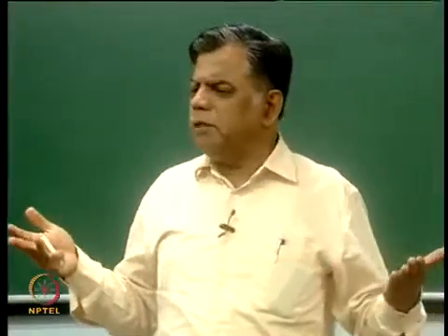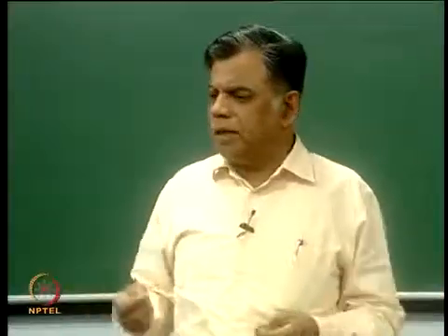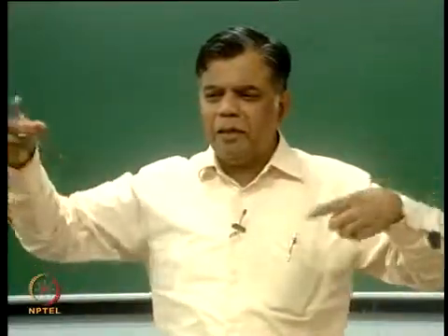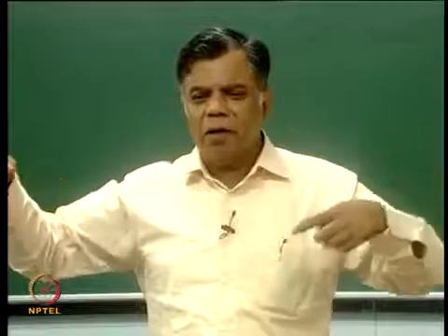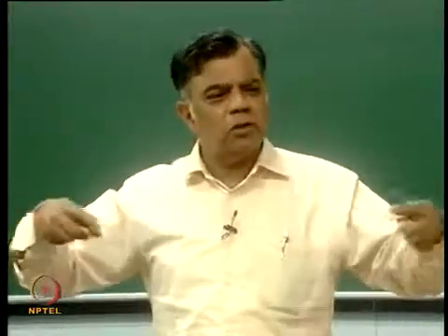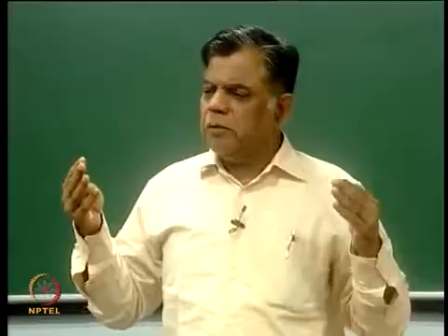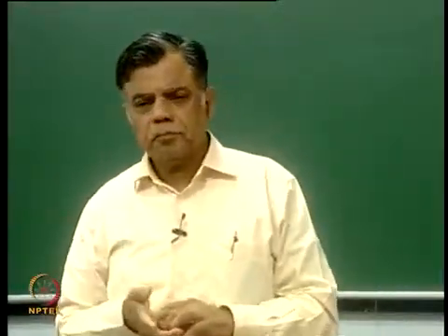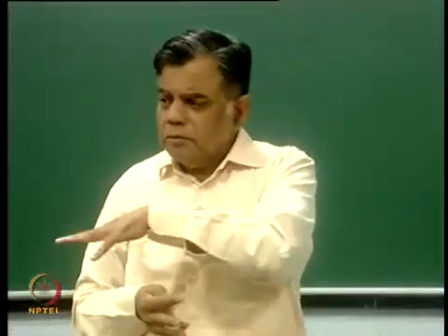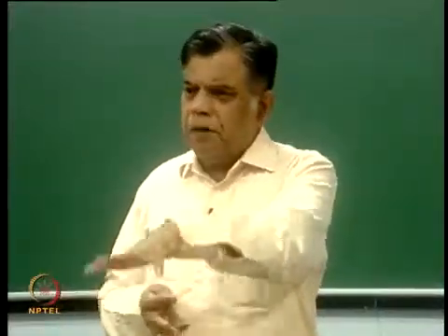u ∂u/∂x + v ∂u/∂y = ν ∂²u/∂y² − (1/ρ) dp/dx. So many mathematical terms he cancelled out with certain assumptions, some very right, some approximately right. But his intent was, can I handle the Navier-Stokes equation in a much simpler way for me to get my skin friction coefficient. That was only from the fluid mechanics point of view.